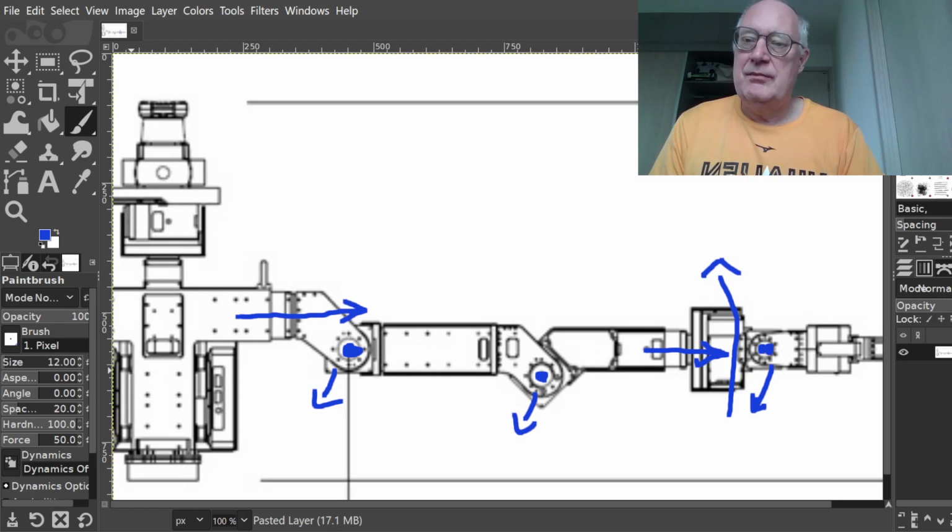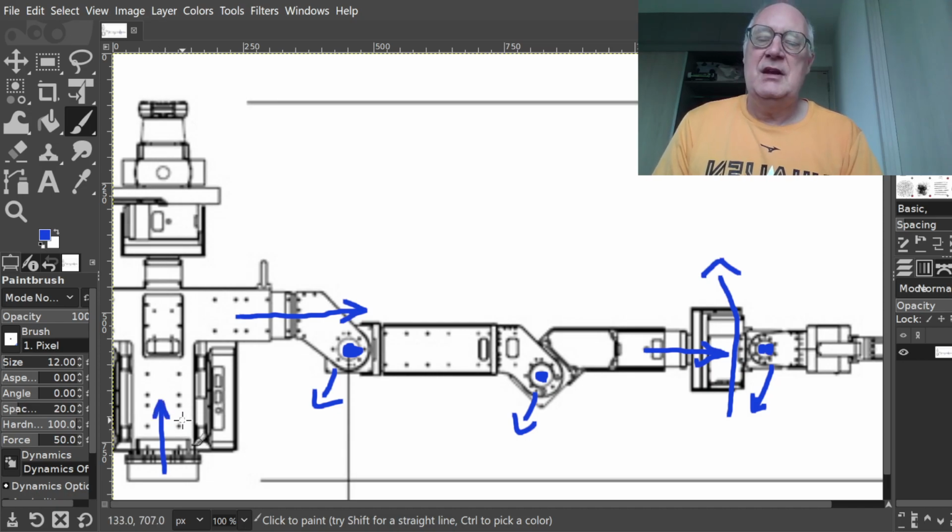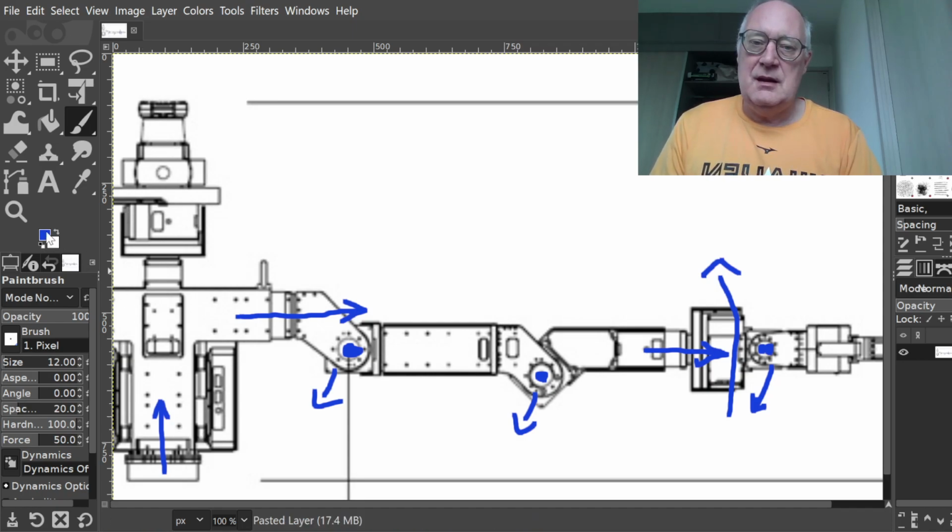So here our inertial frame will be in the center of the torso. Make it here. And then for humanoid robots, like I already said, makes sense to talk about Z going upwards. And then now I have assigned all the Z coordinates. Right? Now I know where the Z coordinates go.